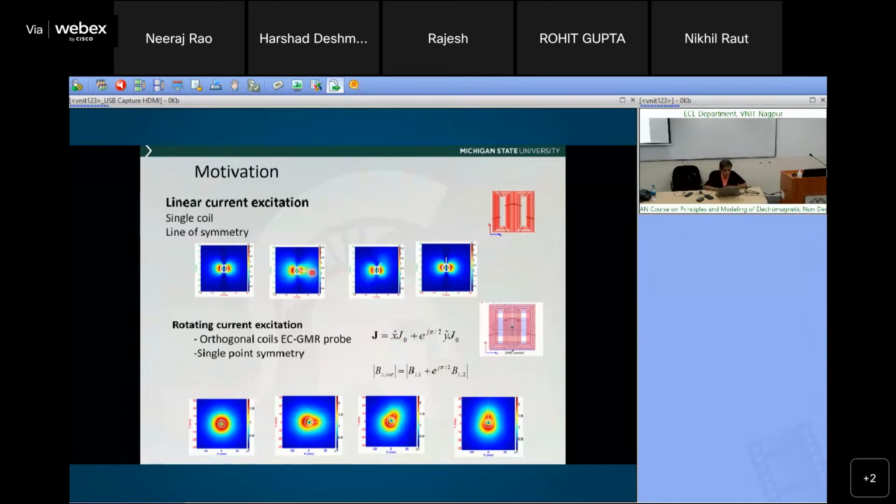Also over here, this is the orientation of the defect. So you can see a lot of asymmetry between the two. In this and in this case, the defect is vertical or at an angle, and you can see that it is already lost, particularly when it is vertical. It's in the dead zone.